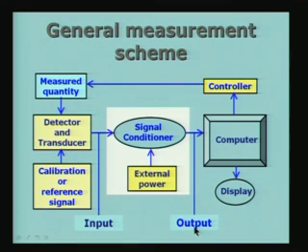Between the input and the output, we have what is called the signal conditioning circuitry. What it does is it changes the input level to the desired level at the output by either increasing the value or decreasing the value, that is by amplifying or reducing the amplitude or the signal magnitude. It may also manipulate in many other ways, for example, by taking the logarithm or integrating the input or differentiating the input and so on and so forth. So, these are all possible conditionings which can be done.